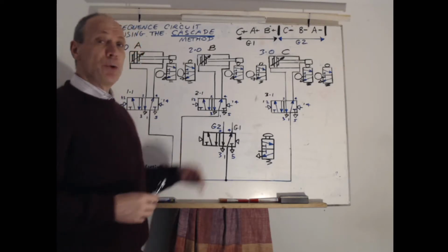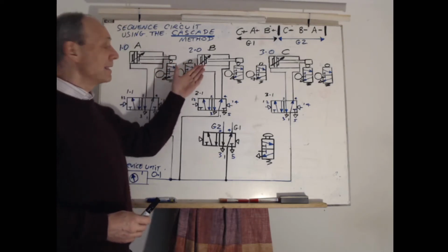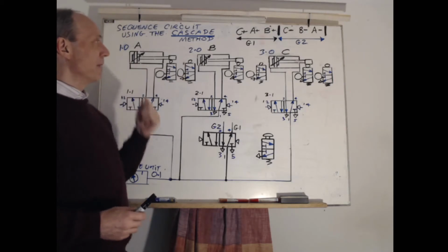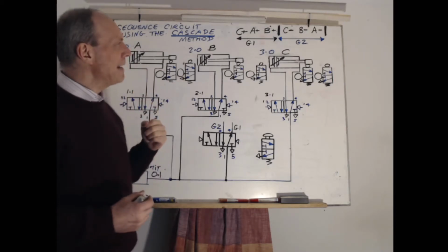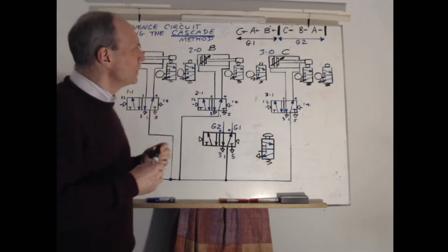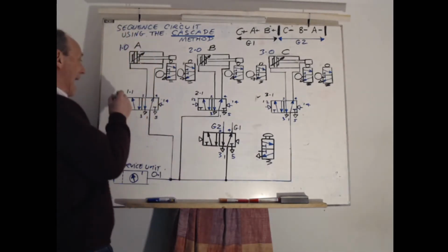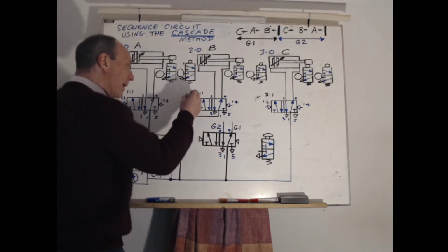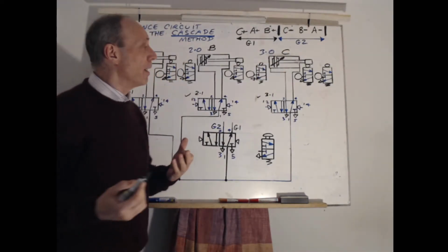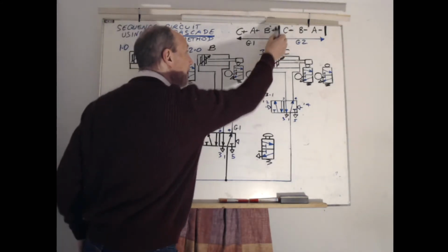If we follow it through, it goes C plus, A plus, B plus, and then C minus, B minus retraction, A minus. But if we think about it more carefully, we have to undertake really the thoughts of where the trap signals are. So if we imagine this, we're going C plus, A plus, B plus, and of course when it goes to C minus, it can't do the C minus because the pluses are already in position. So we know we have a trap signal at that point.